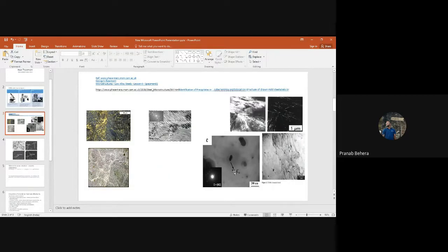This M23C6 means it will show carbon. C means carbon, M means some metals. It may be molybdenum, chromium, and iron, right? So it will show some peaks. Let me show you some index result. Otherwise, if you are getting confused, I'll show you later. Otherwise, I have not much time here. You understand? That means you can easily determine the composition of that particular particle.